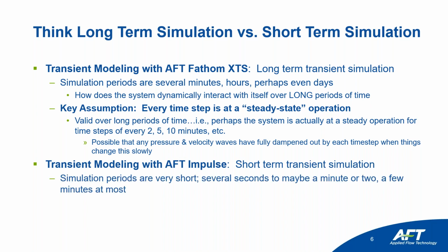So the simulation periods are very short in Impulse. You're typically going to be looking at what happens 10 seconds to maybe 30 seconds after a sudden event, like a valve closure or a pump trip or something like that. You might model out to what's happening a minute or two after an event, or maybe a few minutes at the most. But overall, what you want to see is what's happening in that very short period of time during a sudden pressure surge event.